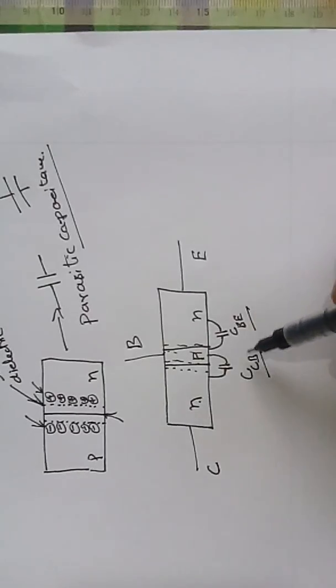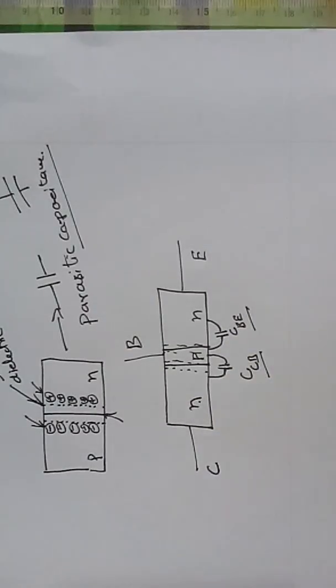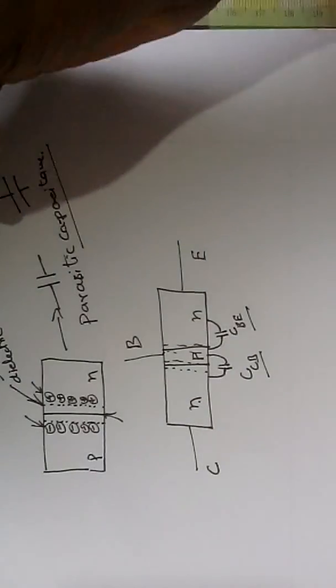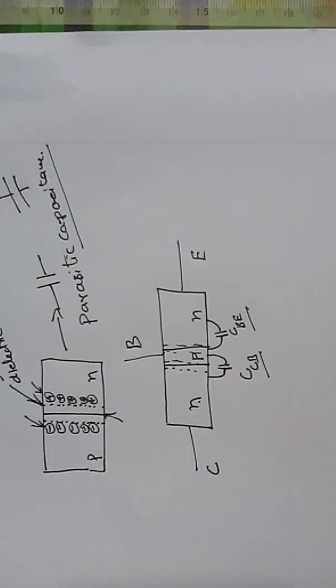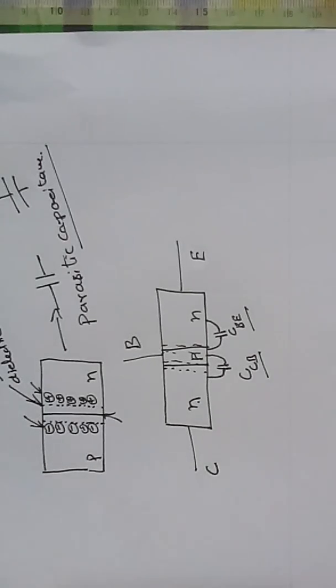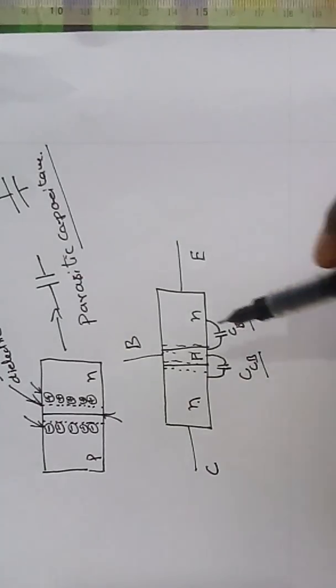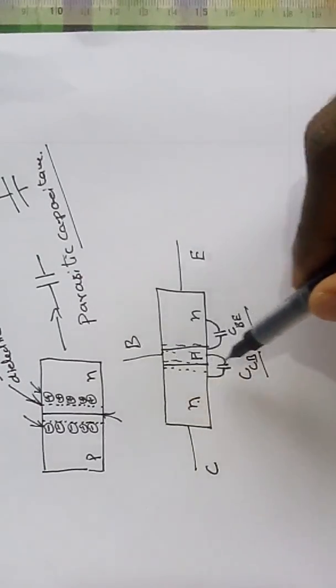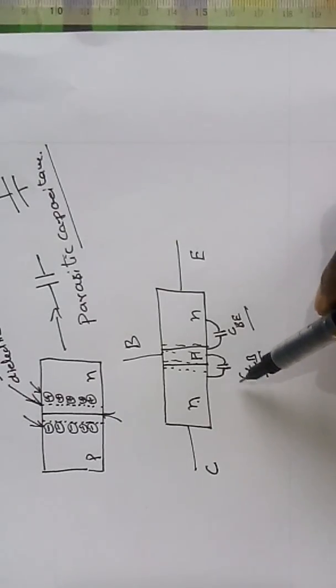These are called parasitic capacitances. Here we are not connecting any lumped capacitor as we discussed in the previous case. In the case of resistors, you might have seen that the resistance value is independent of the size of the resistor. But in the case of capacitors, if the dimension of the device changes, then the capacitance will change.